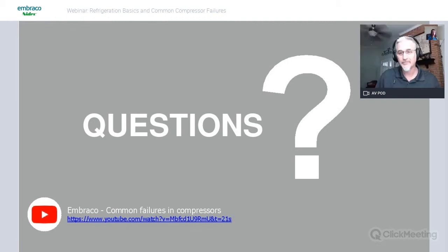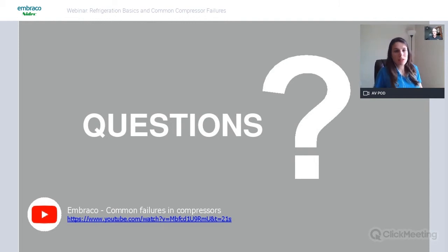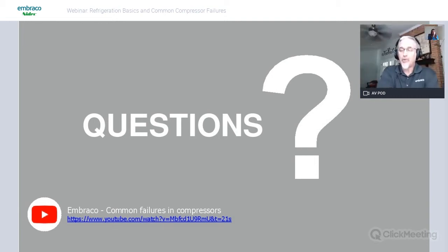And another question about the loud noises from Joel from Canada. What happens when the cooling unit's temperature goes high and the fan is loud? Sounds to me like either an evaporator or a condenser fan could be damaged or malfunctioning, and probably more likely the condenser fan.